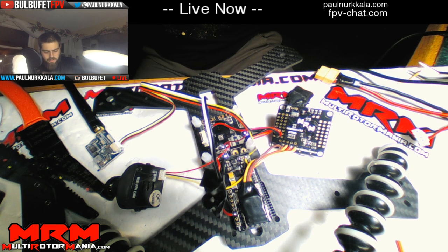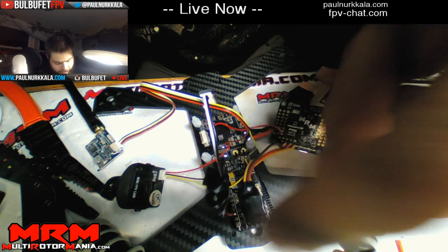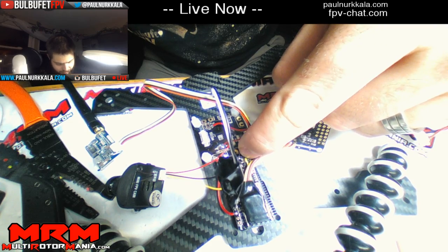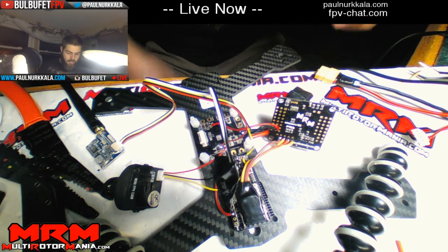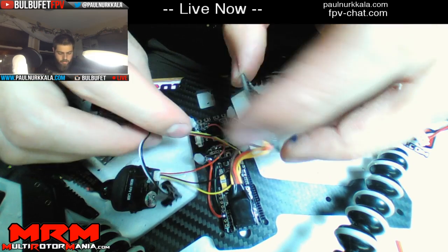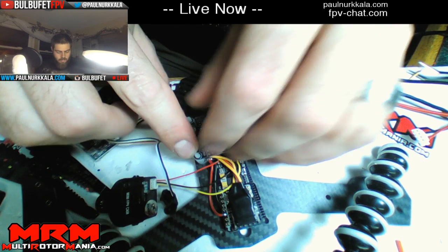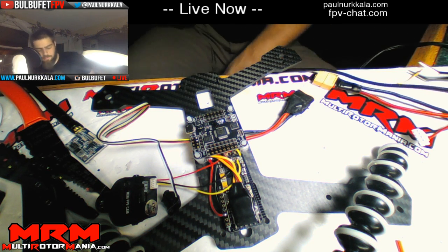Video out is on the outside, and that is the outside, so we're good there. And then for the camera, we have video in on the inside. We've got ground, and we've got power. All right. I'm going to go ahead and drop this on top of all of that. Looks a little better once you get that in there. And that's powered, and that's connected to the OSD.